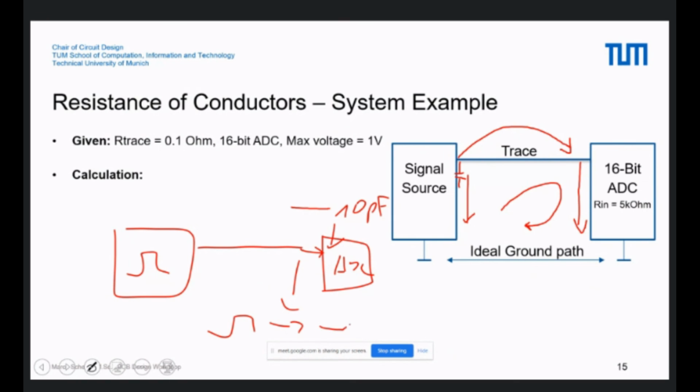What you get is a clock like this, if you have a long wire here. And this you can also simulate with KiCad. So put a clock source here, a long wire, and then measure the clock at this point.